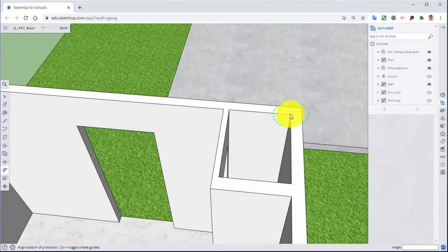Click in order to create the center point right there in the corner. We're going to drag over to the left and click again. That sets the 0. Without clicking on that one, we have nothing to reference from. So this is the R0. So now anything going up is going from 0 to 20 degrees, 30 degrees, and so on, as you can see down here in the lower corner. And then going down is the same. So we got 20 degrees, 30 degrees, 45 degrees, etc.